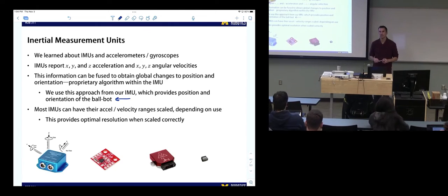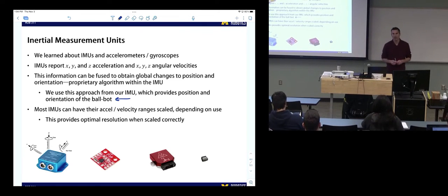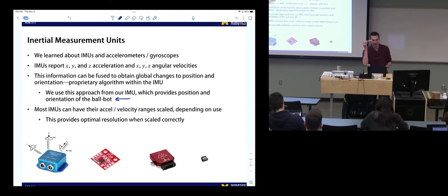Because you have to integrate over those terms, and especially if you have noise, it just accumulates a bunch of drift and can cause very inaccurate results very quickly. That's right. Even if you have a signal that's really, really accurate, but not perfectly accurate, and you integrate that signal, it will become very inaccurate. So that's what's happening here.